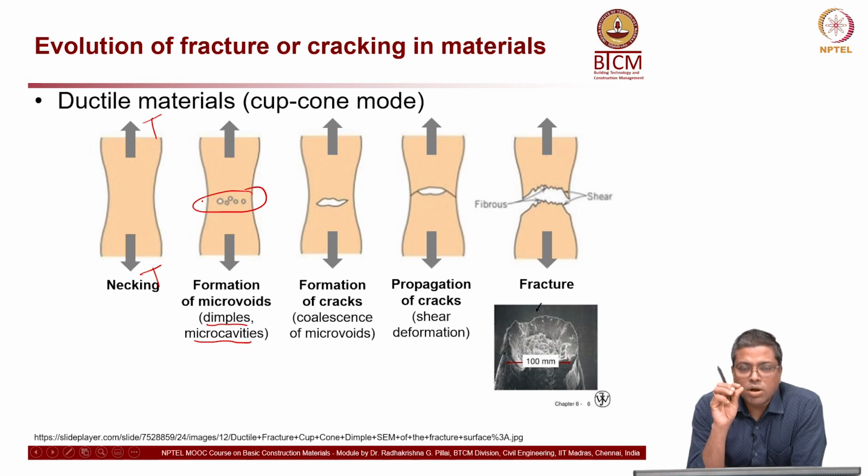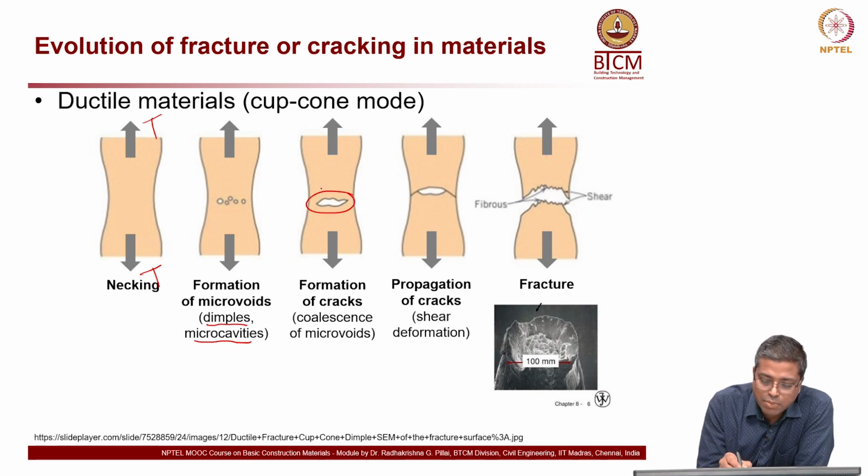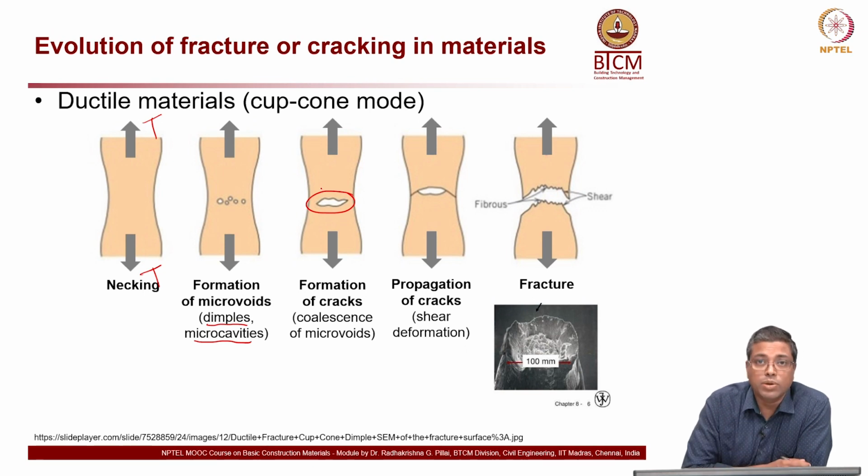Now, with that small deformation happening there, eventually, as more and more force is applied, all these micro voids tend to coalesce and become one macro void, or it forms a large crack. Visually you will be able to see the crack happening.